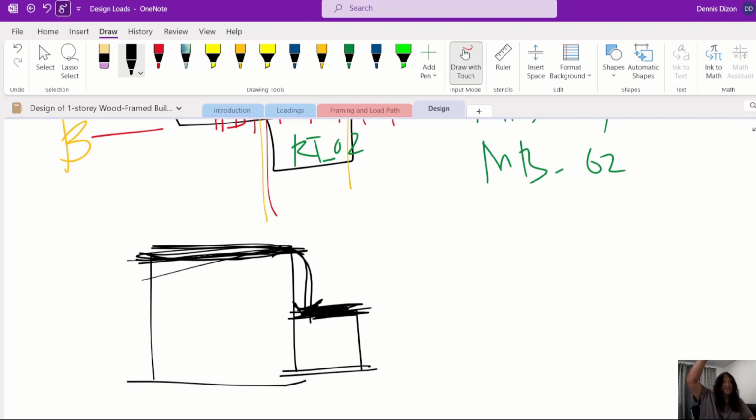Now, if you have, for example, a really high parapet, right? Imagine, and then your location of your scupper is really high. So there's a possibility it will be like a swimming pool on top of your lower roof or vestibule. It happened in one of our projects, at least one that I can remember.